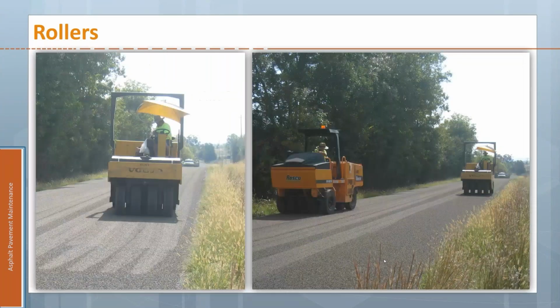And here's a couple more pictures. You can see how that gets rolled in, and then you'll stagger those pathways as you move forward and backward for the different passes. Make sure that all of it is getting compacted and seated within the binder.